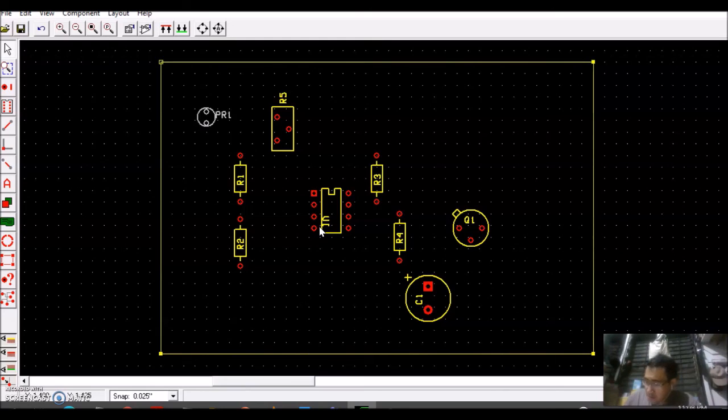To create this part we would start with the capacitor base again, this time with a lead spacing of 0.6 inches or 15 millimeters. It is best to use a polarized capacitor base as the buzzer is polarized.